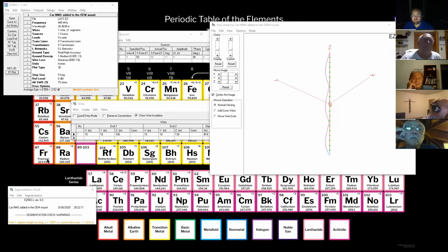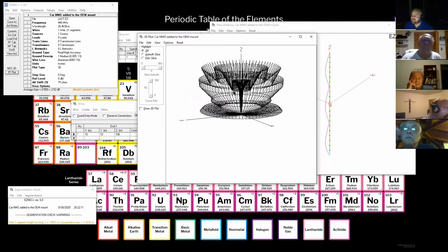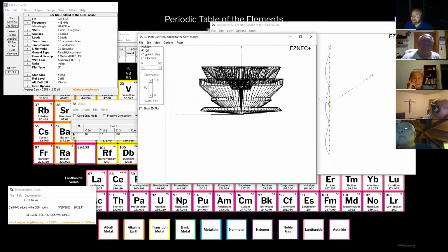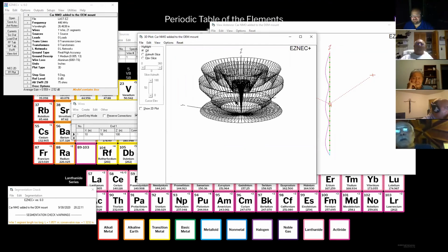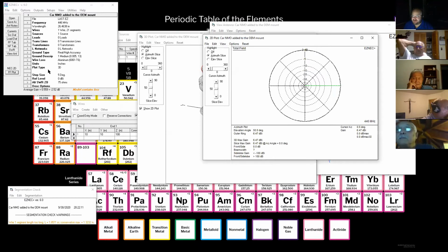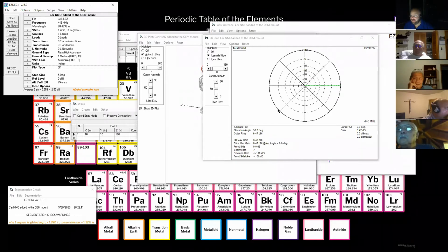So when it calculates the far field plot, it's going to take this frequency that I put up here, and it's going to calculate this pattern. So this is roughly what the pattern radiating from the antenna is going to be. Now it's kind of blocky, and it's hard to make sense of. Now I can say I want to see the azimuth slice, and this is the peak of the azimuth gain right here at 50 degrees, and say, show me the 2D plot instead. And the reason I'm getting this 3D plot is because I told it this is the plot type I want, is 3D. I prefer 3D because I can always get the 2D plots right out of it, but you can't in this thing go from a 2D plot to a 3D plot. So that's why I started here.